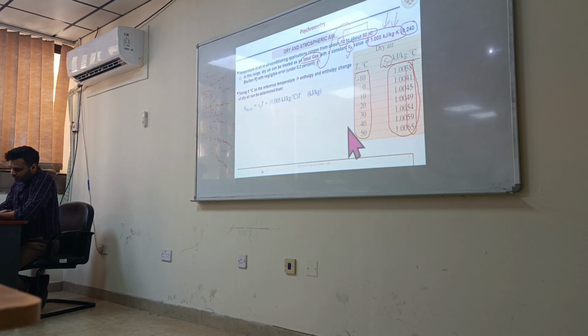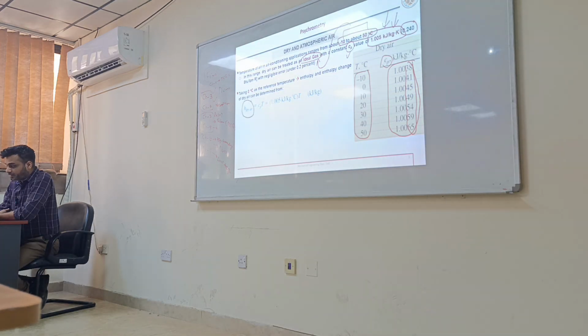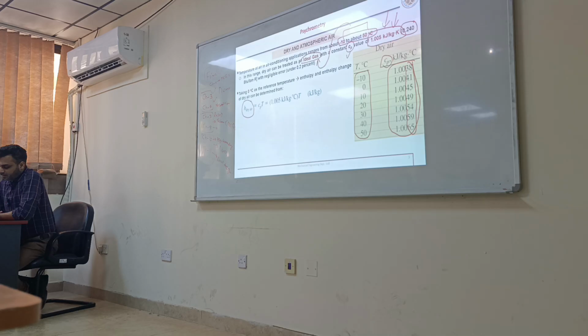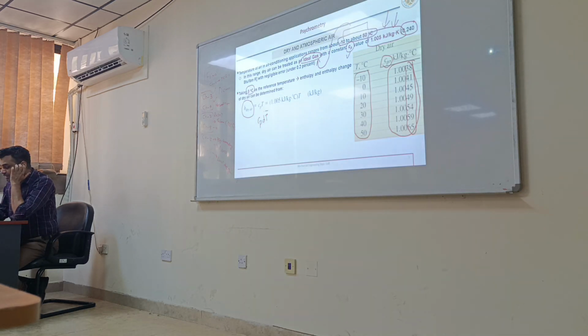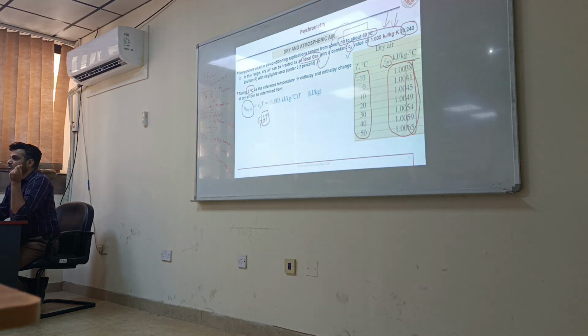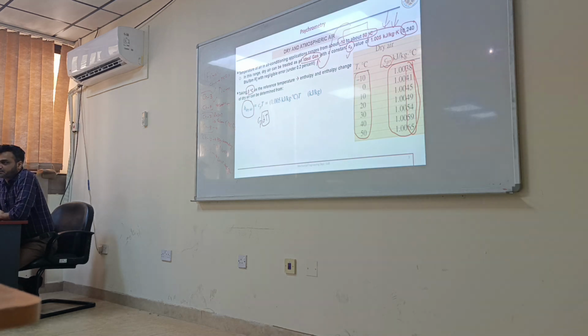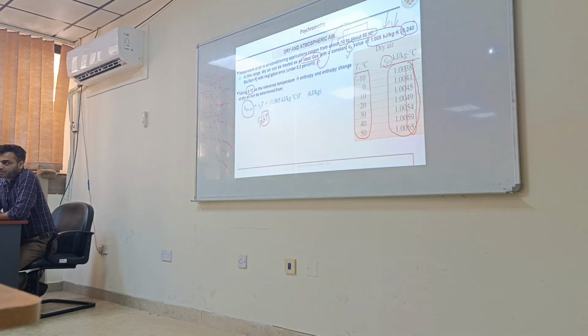Okay. What about the enthalpy of dry air? Dry air means without any water vapor. So for enthalpy, we always take some reference to define it. So actually it is the integral of Cp dT. But here one of the T is 0 degrees Celsius. Here he is specifically mentioning Celsius. Whenever there is dT, Celsius or Kelvin doesn't matter. And one of the T is 0 degrees Celsius.